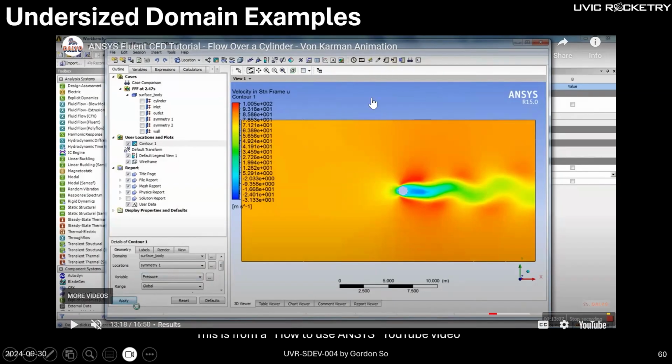And when I say mismatch, it's because maybe you define this as a far field, but far fields should be uniform, right? But the flow actually is not uniform here. So that's a mismatch between conditions. So this is not big enough.